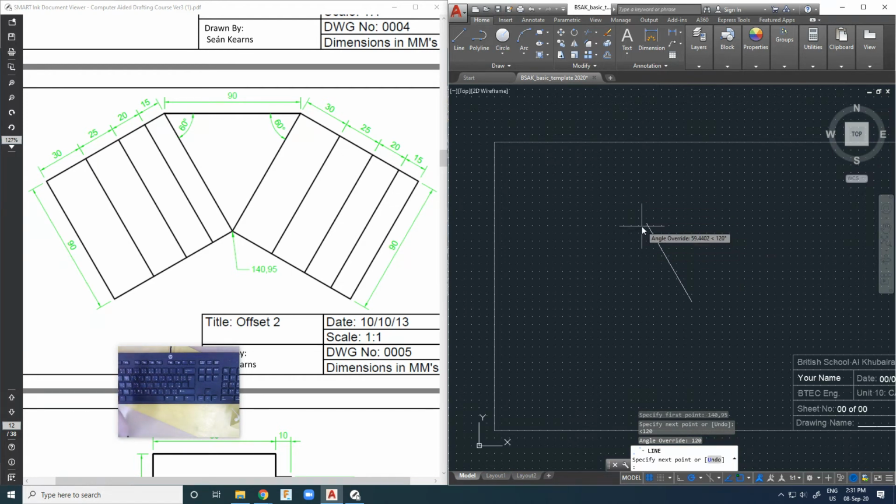Okay, so in the second quadrant, basically, going up at a 60-degree angle. And the distance for that is 90, then an angle of 0. Just make sure you get the angle button. I don't know, is it my laptop or is it AutoCAD in general, but that greater than symbol doesn't always want to show up on screen. So angle is 0, enter, and then the distance is 90, enter, and then C, enter to close.